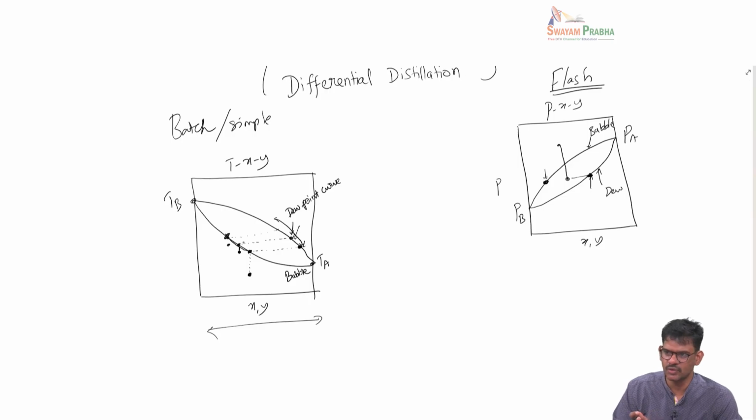So that's why it actually goes a little bit away from the bubble point, but then you're constantly applying heat. Yeah. So if it's an azeotropic mixture, the two curves will be the same curve, right? The two loops will actually converge into the same line. So then when you vaporize, the vapor and the liquid have the same composition, right? So no matter how much vapor you take away, the liquid will always have the same composition.